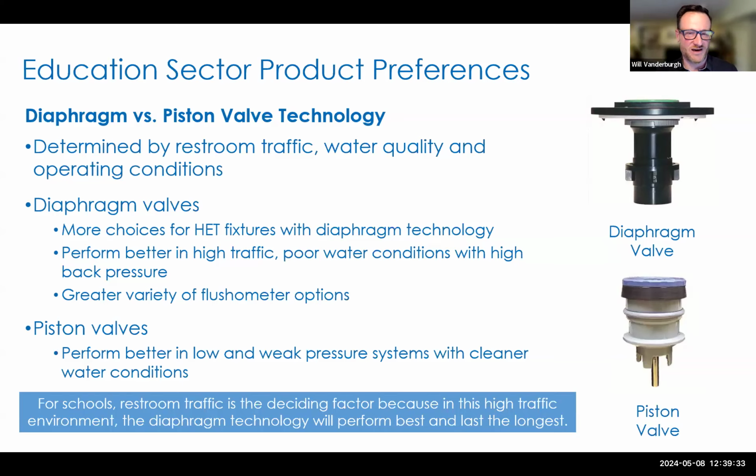But as soon as you open that valve, if there isn't enough flow to replenish it, due to line size or obstruction or whatever that reason might be, the pressure will fall off and the fixture won't flush properly. So when that valve is open and running, a minimum of 25 psi. Piston valves, we've seen them operate even as low as 15 psi quite happily.